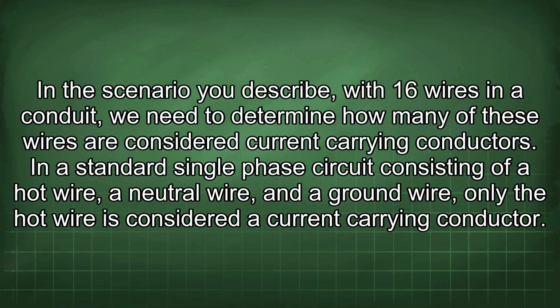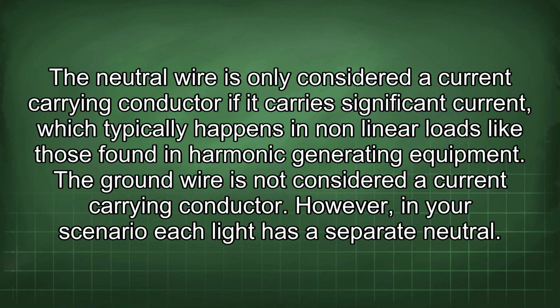In a standard single-phase circuit consisting of a hot wire, a neutral wire, and a ground wire, only the hot wire is considered a current carrying conductor. The neutral wire is only considered a current carrying conductor if it carries significant current, which typically happens in nonlinear loads like those found in harmonic generating equipment. The ground wire is not considered a current carrying conductor.